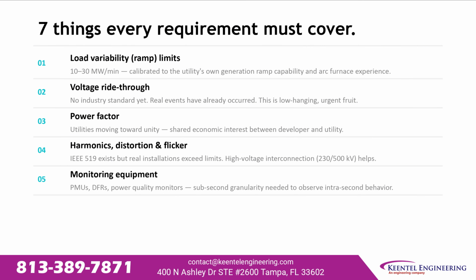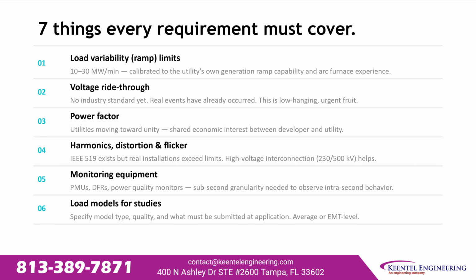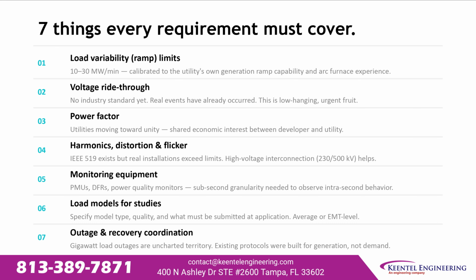5. Monitoring equipment. PMUs, digital fault recorders, power quality monitors, sub-second granularity required. 6. Load models for studies. Specify model type, quality, and submission requirements at application. 7. Outage and recovery coordination. Gigawatt load outages are uncharted territory. Existing protocols were written for generation, not demand.